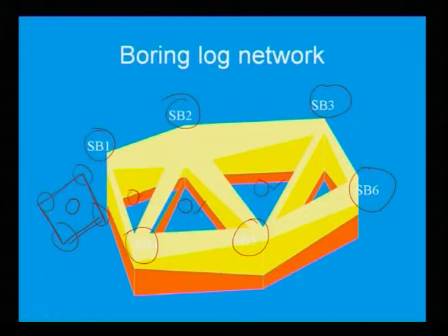Generally you go around the periphery of the proposed structure, because the foundation will be lying here, column and beam will come at the corner, maybe at the center, at the periphery, so that you will know what the soil profile is.